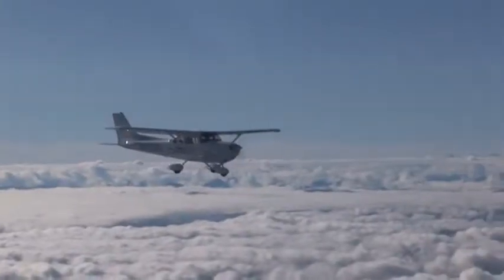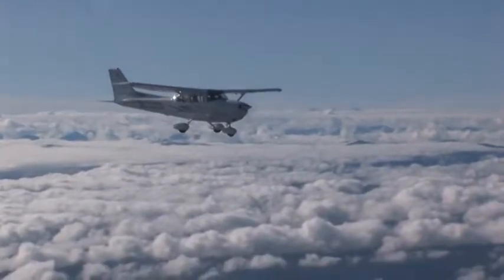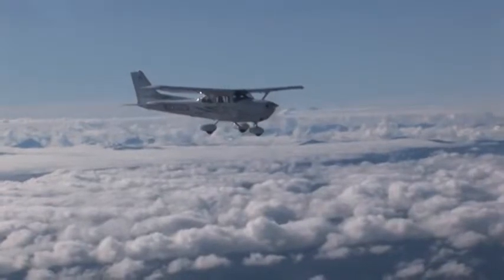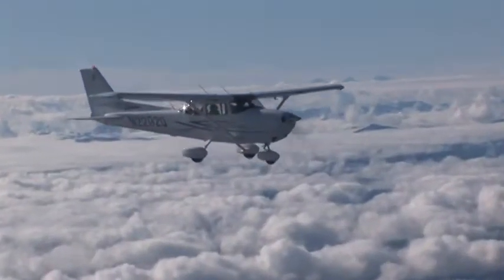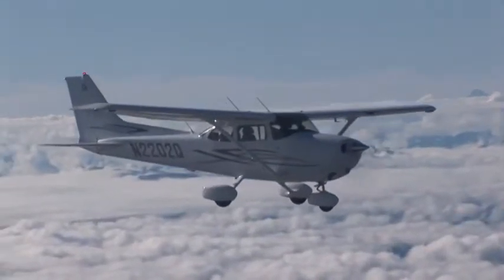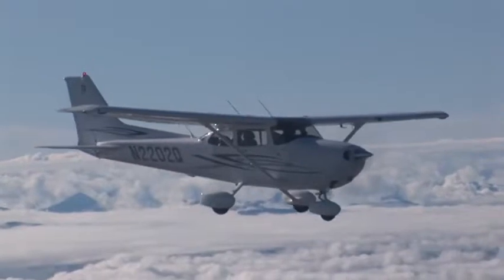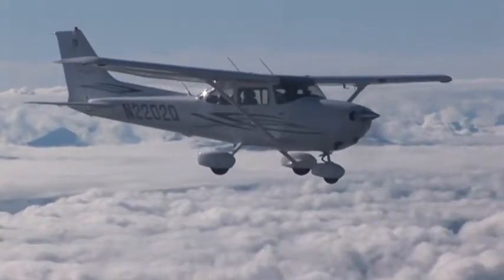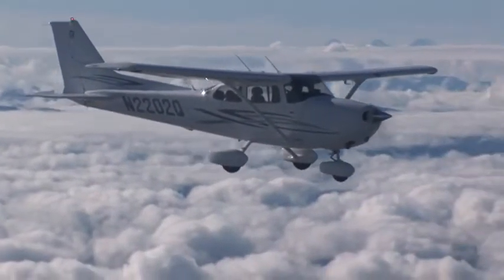When flying at high altitudes, the air is less dense. This may cause the fuel-air mixture to become too rich if it is not properly adjusted. A rich mixture is one in which the fuel-air ratio has too much fuel for the given volume of air that is entering the cylinders. Therefore, the pilot should lean the mixture, in other words, decrease the amount of fuel flowing to the engine. This action compensates for the decreased air density.